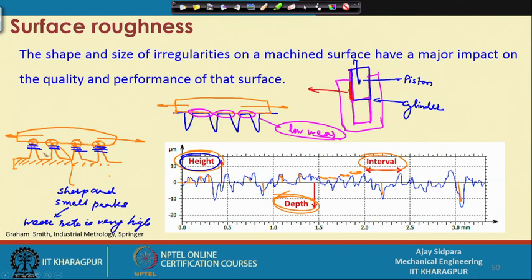If this interface surface is something like this, then the wear rate will be very, very high, and after some time you will have some type of opening between these two. It will not be a completely smooth fit. So, your piston and your cylinder surface will be something like this, a very, very large magnified view. So, after this wear, what is going to happen? This is going to happen in this case.